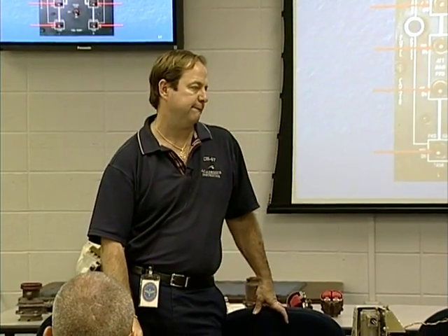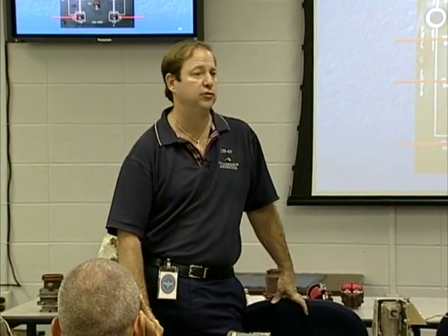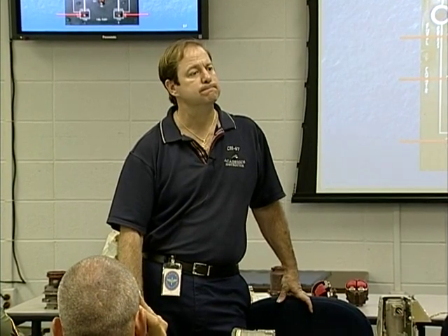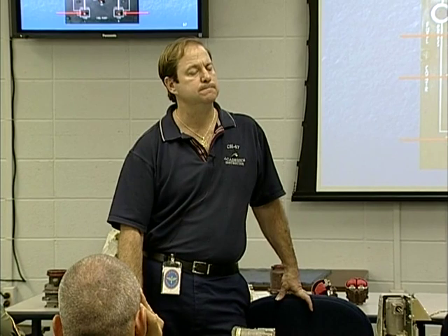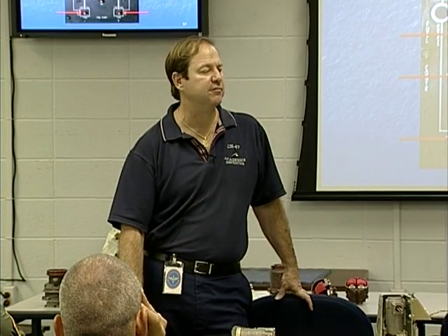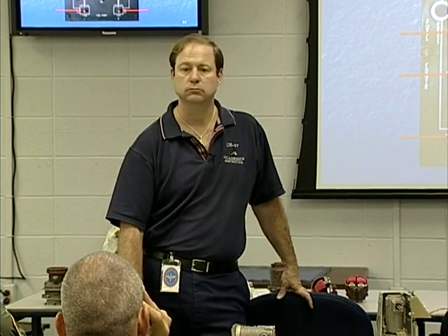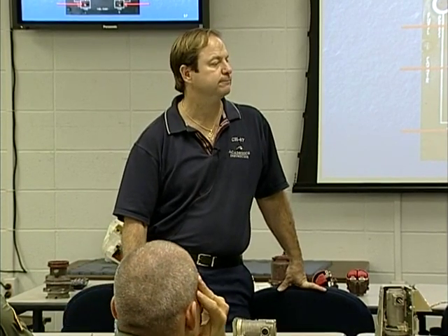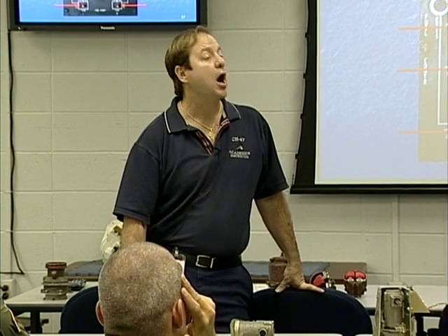Fuel venting. Fuel venting, yes sir. What else? So for an emergency procedure. When else? Crossfeed. No, not what I'm looking for. When would I have to turn those pumps off? And what pumps would I have to turn off? Internal loads? Not internal loads, no. Oh, you have to turn off your aux tanks when you're refueling with the IRFs.